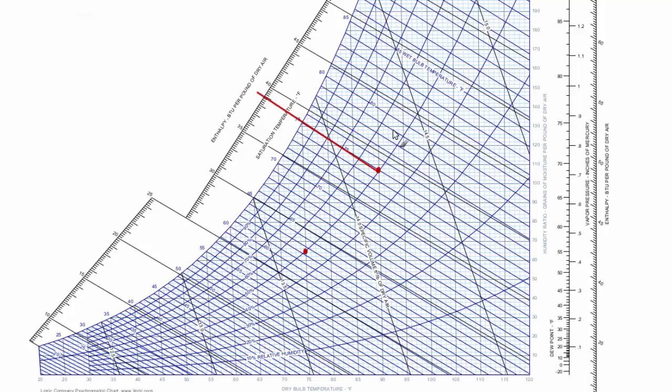But it's helpful to know that these are the two points, because for any quality, whether it's temperature, enthalpy, humidity, whatever the case may be, if you're mixing two streams, then the quality of the mixture must be some point along that line. That's worth noting.